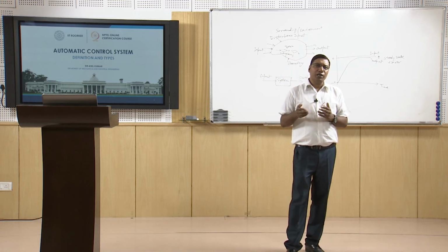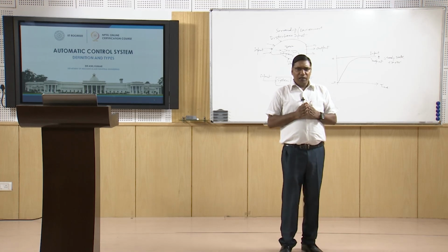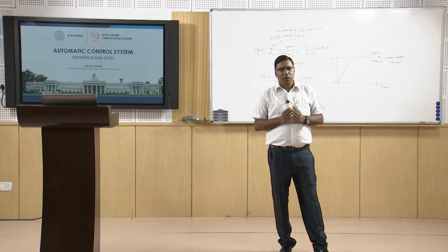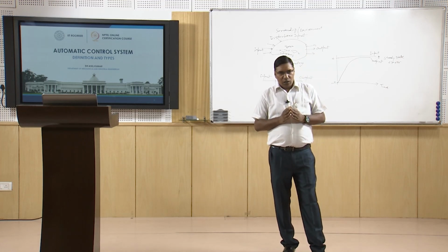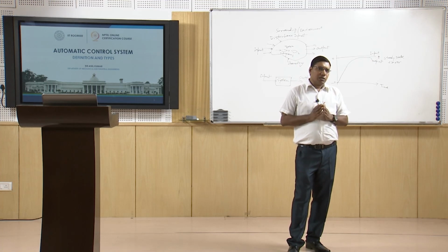And therefore we see that in open control systems, there is no facility to monitor how much the output is different from the expected, and how to counter the disturbances that are entering the summing junctions, at the input and output of the process or plant. So these systems cannot compensate for disturbances.